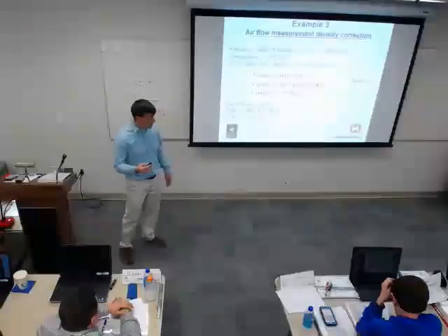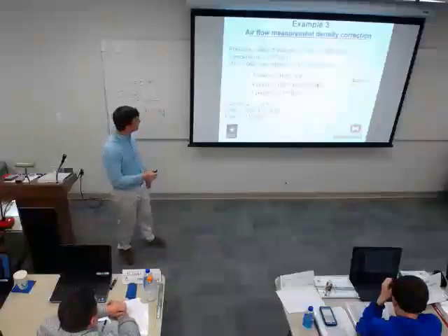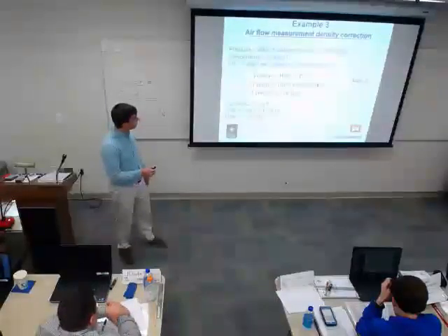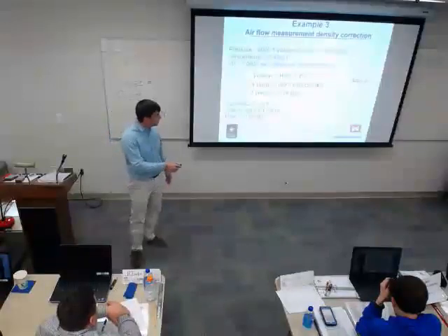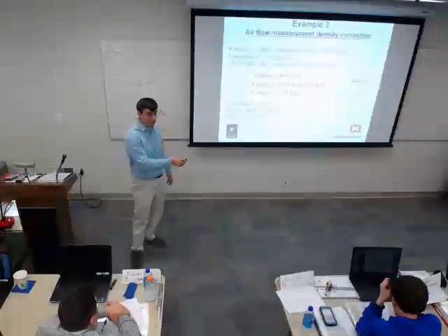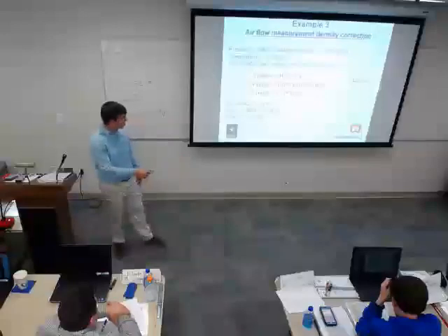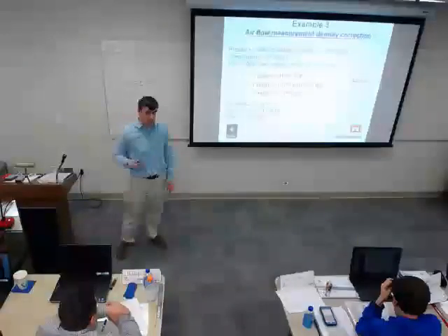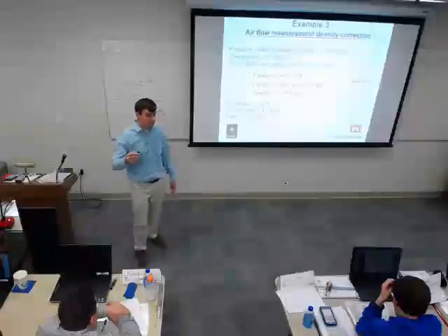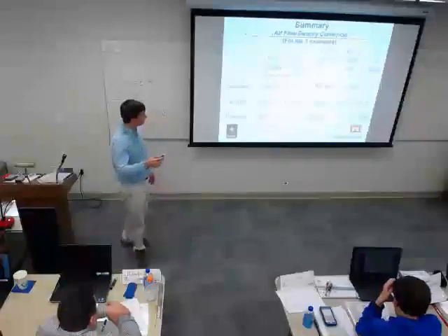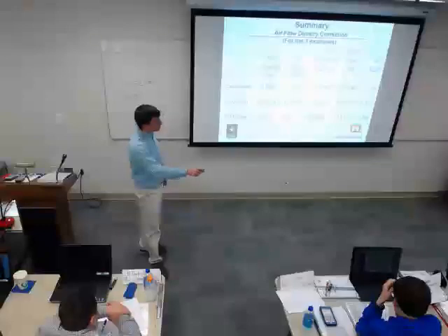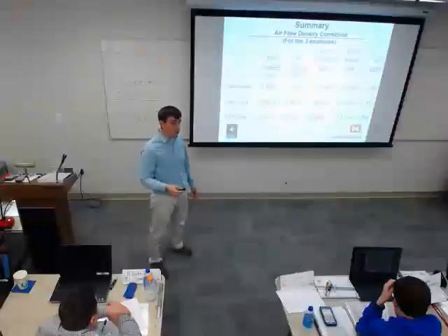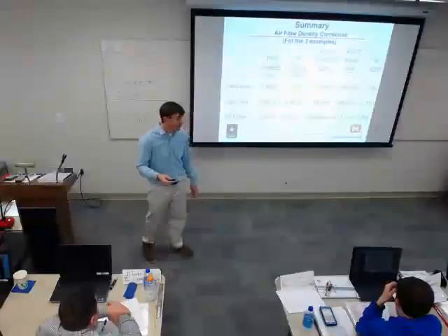Now let's go to Denver and do the same reading, 6,000 feet, 70 degrees, same velocity pressure, plugging in that different density in this example. Plug your way through it, 1,100 CFM. Everybody okay with that? Let me show you that table. This is just a table of what your error would be if you don't correct for altitude in those places.